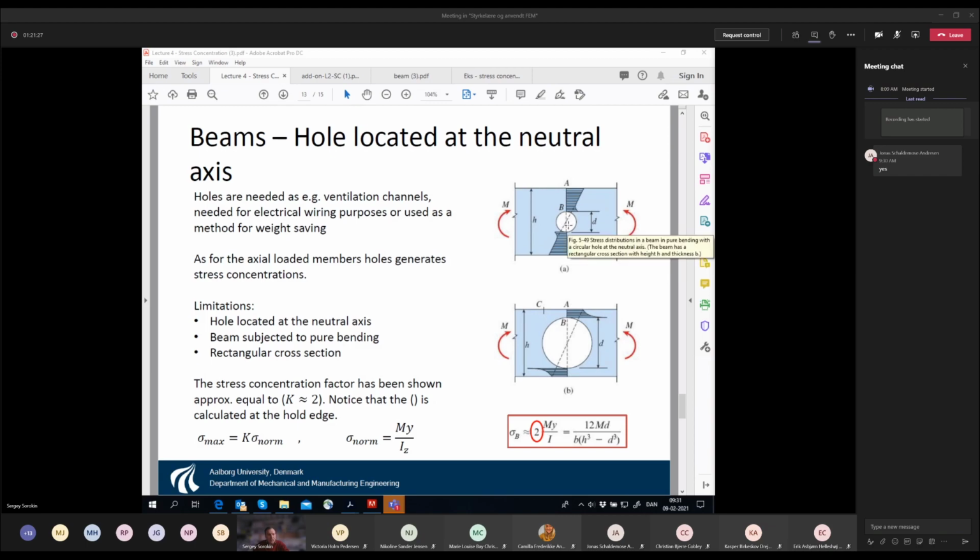And then there are only two possibilities. One is that the stress due to the concentration is less than the conventional bending stress, and then we assess strength based on the stress at this point A. Or the hole is large, so that the stress concentration overshoots the maximum stress in bending.